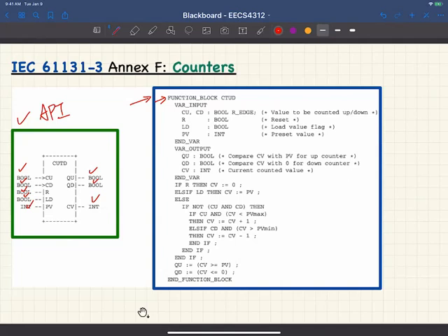Don't forget one thing. Imagine over time, let's say this is a function block, counter. You're going to invoke this many times, right? Once you invoke that, you're going to go back and invoke it again, because whatever output it is currently is going to be the input for the next run. It's going to be invoked continuously.